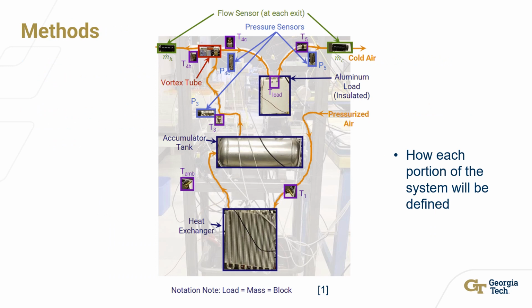Station 1 of the system measures the compressed air into the system. A heat exchanger between stations 1 and 2 cools the air to ambient temperature. Pressure variation is then removed between stations 2 and 3. Station 4 creates both hot and cold outputs. And finally, Station 5 measures the flow of outputted air and vents the air.